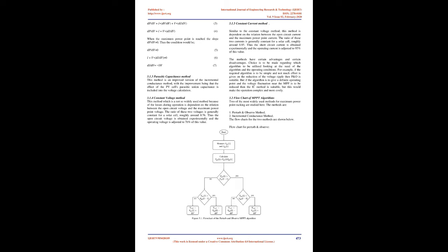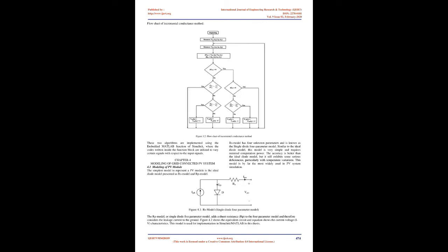Conversely, the maximum voltage is produced when there is a break in the circuit. This is called the open circuit voltage, abbreviated VOC. Under this condition the resistance is infinitely high and there is no current, since the circuit is incomplete. These two extremes in load resistance, and the whole range of conditions in between them, are depicted on a graph called an IV, current voltage, curve.